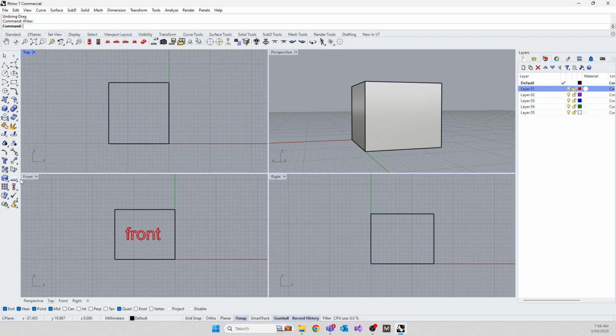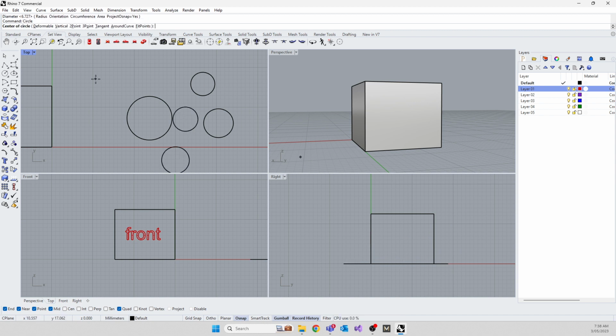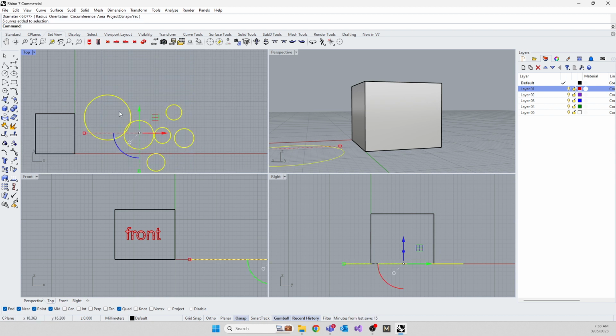Okay, so how I did that was any command in Rhino. If you type the command, I'm going to do one over here. Or it doesn't matter how you made the command. I'm going to make a circle here. And this circle is asking me to select a center point and a radius. I'm going to click it. You can repeat the command by immediately afterwards pressing enter, or by clicking the right button. So if I click the right mouse button now, look at the command line. The last command performed showed up again. So that's handy. I can quickly, by just using the mouse button, not having to type the command again over and over. That works for every command in Rhino.